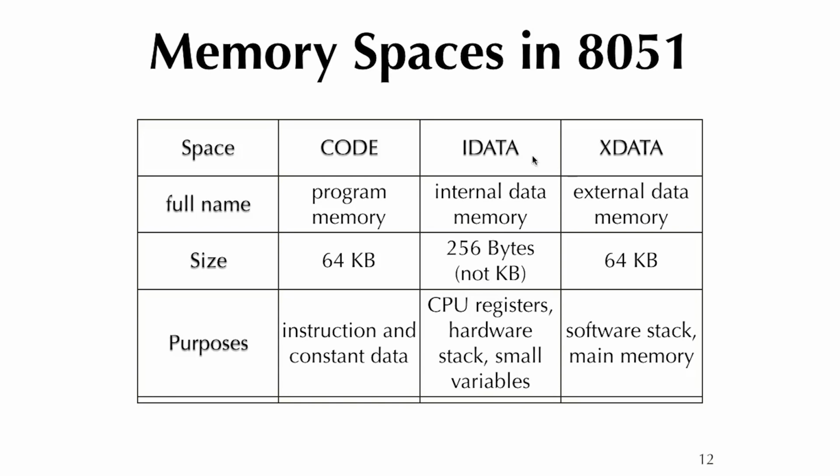Well, it turns out, yes, in complete terms, it's 256 bytes, but then half of the 256 are reserved for special function registers. So your P0, P1, P2, they are in the upper iData space, and they are really not just for data, they're for special function. So your real data is only the lower 128 bytes, okay? And in fact, some of them overlap with CPU registers, and other things, but we'll get to see those.